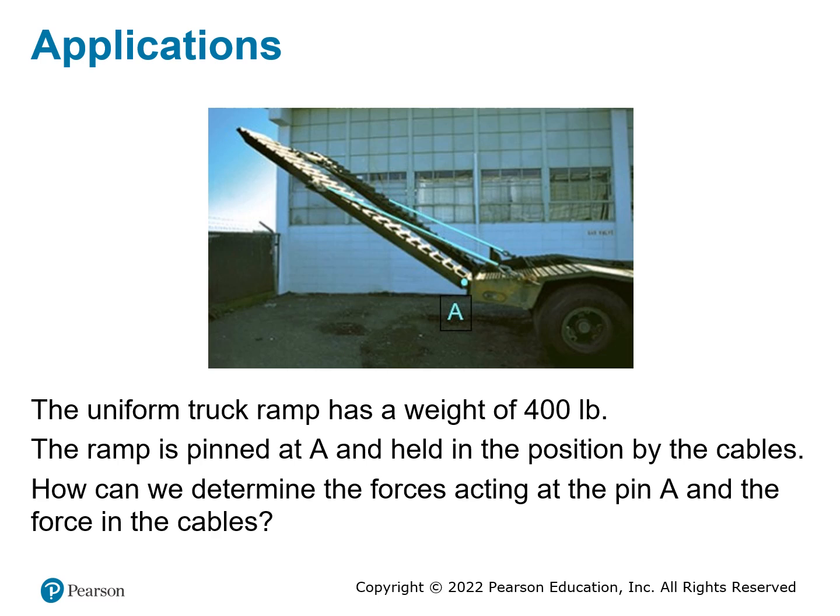To start with an application so you will understand what we are talking about, we saw this picture before. Point A is what? It is a pin. So what is the function of the pin? A pin will give support in the X and Y direction. However, it will allow the object to rotate freely. If this can rotate freely about point A, then you will not have any reaction moment at point A.